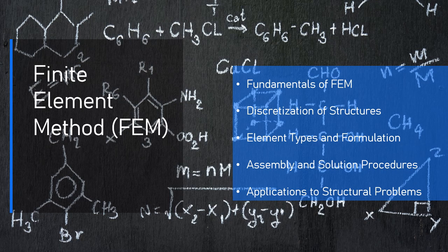4.6. Post-processing and results interpretation. After solving for the displacements, the next step is to interpret the results. Common post-processing steps include calculating internal forces and stresses. These are derived from the displacements using the element stiffness matrices.